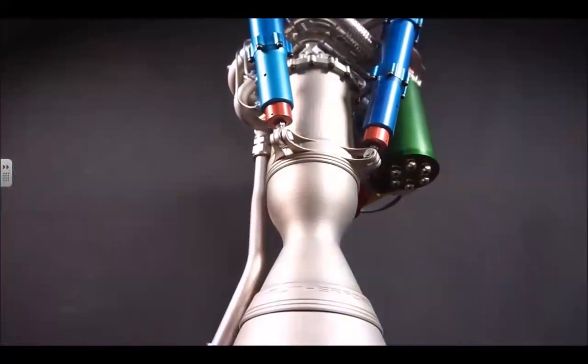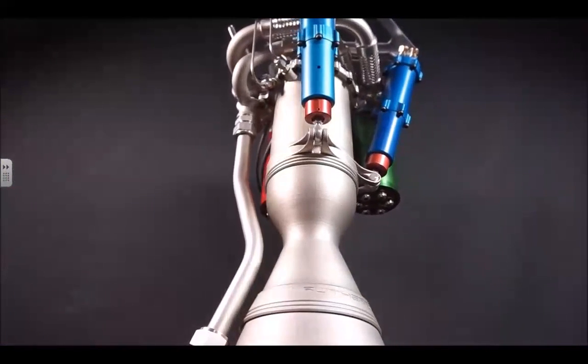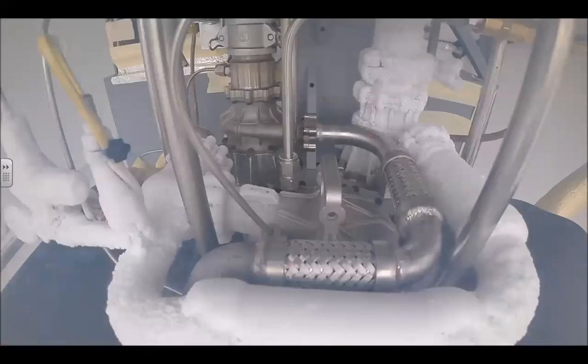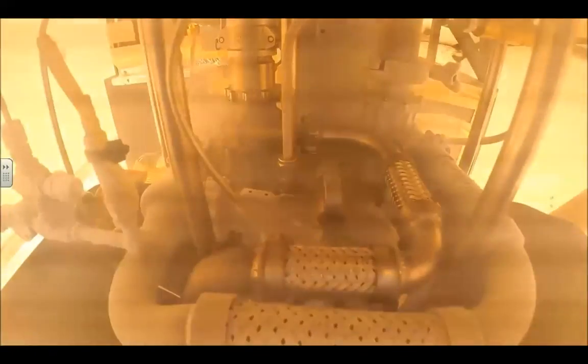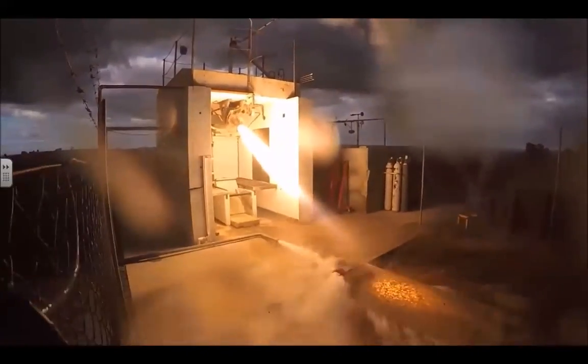But how do you drive these is really the next question, because you need a lot of power to drive this to get the fuel to come through it as quickly as possible. If you look at an in-development rocket, a small rocket called the Electron, its engine is called the Rutherford engine, and that is rather unique because the fuel pumps are powered by electric motors, 50 horsepower electric motors driven by batteries, and they will take the fuel and push it through into the engine at high enough rates.